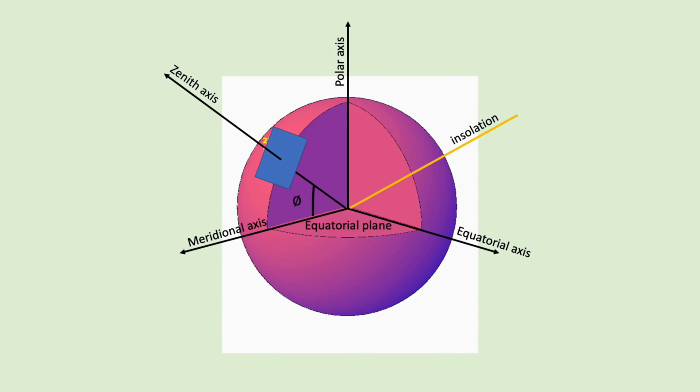The other axis emerges from the origin on the local point on the horizon plane, along the meridional axis and orthogonal to the zenith axis, going down to the south. This line is tangential to the meridian at 77.5 degrees east and is denoted by S, which represents the south direction. The third coordinate axis, which is orthogonal to both the zenith and south axes, is extended to the east, so it is named the east axis.